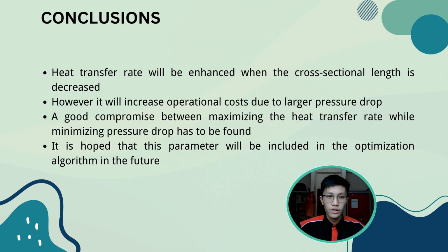In conclusion, heat transfer rate will be enhanced when the cross-sectional length is decreased. However, it will increase the operational cost due to a larger pressure drop. Therefore, a compromise between maximizing the heat transfer rate while minimizing the pressure drop has to be found. Lastly, it is hoped that this parameter will be included in the optimization algorithm in the future.